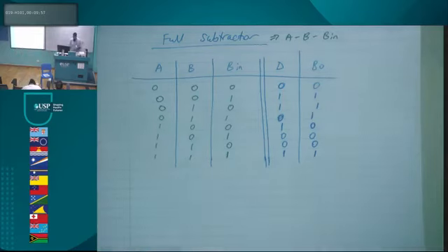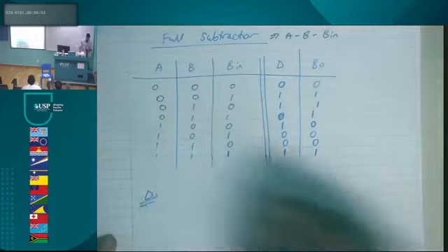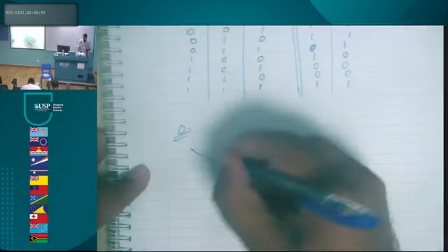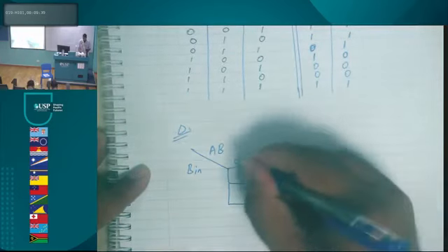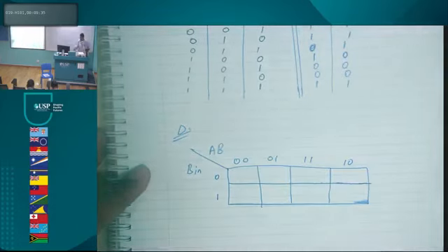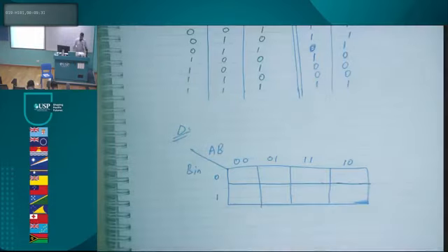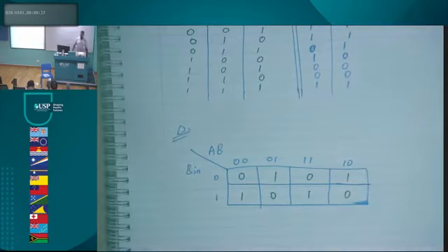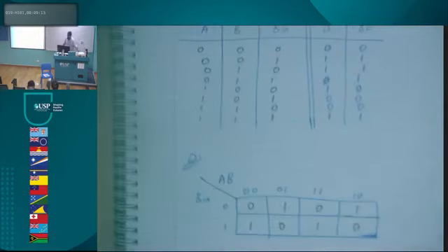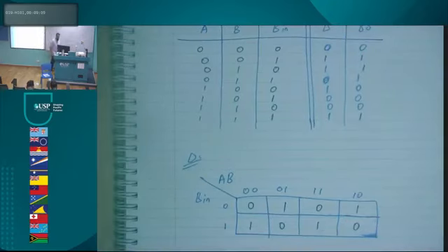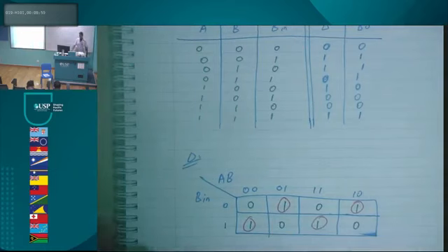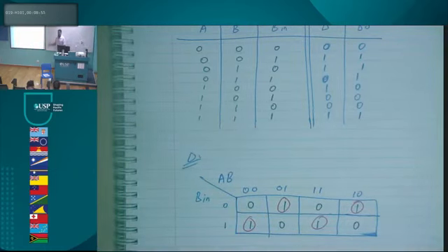Now, of course, let's now look at the truth table for D. And we did this yesterday as well, guys. I'm just looking at the D column over here. All right, we end up something like that. I'm pretty sure you're familiar with how to translate this D column into this Karnaugh map over there. In this case, there's no groups. And if you remember, didn't we find this similar pattern yesterday? Yeah, we found a similar pattern yesterday when we were doing the full adder.